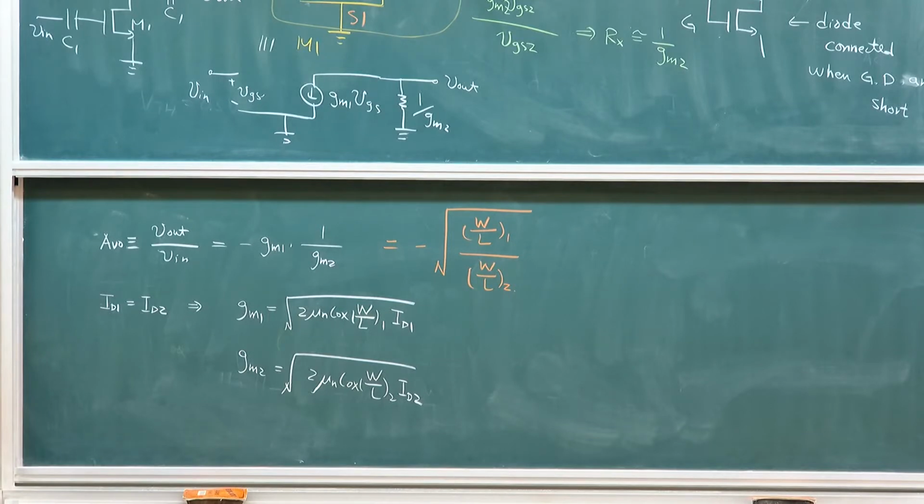For example, the gain at this level may be smaller, and there will be higher gain at this level when the current is lower. Because we know that the gain depends on a square root, typically, with this type of gain, the voltage gain has a bias dependency. Therefore, once my biasing point changes or my signal is large, meaning the current level changes, that will then lead to some nonlinear distortion of the signal.